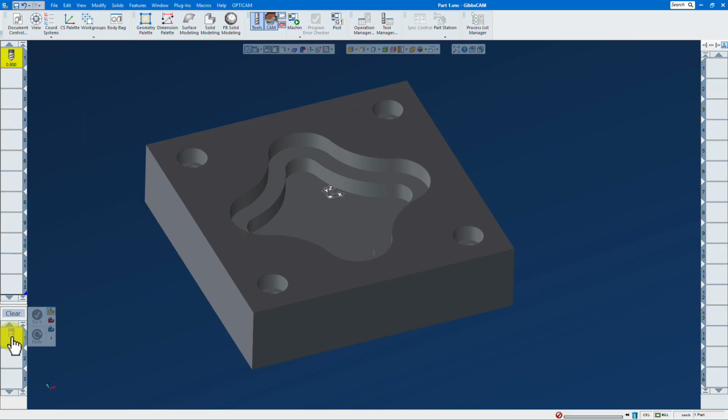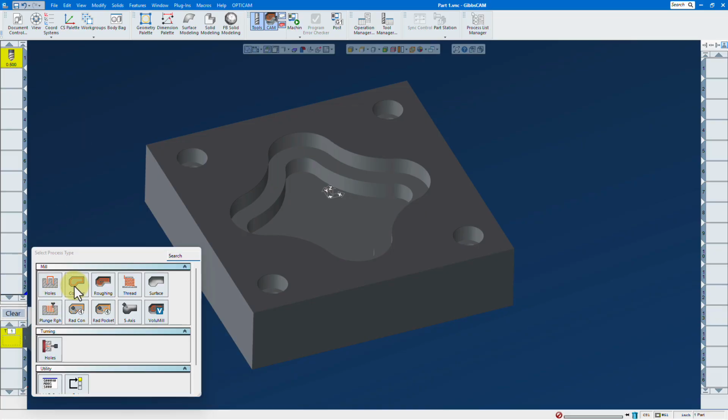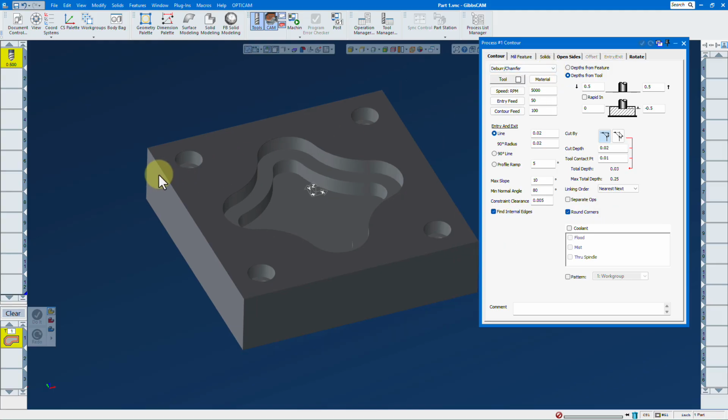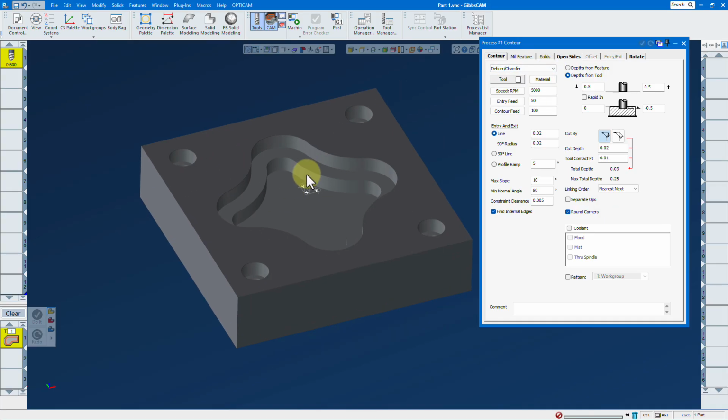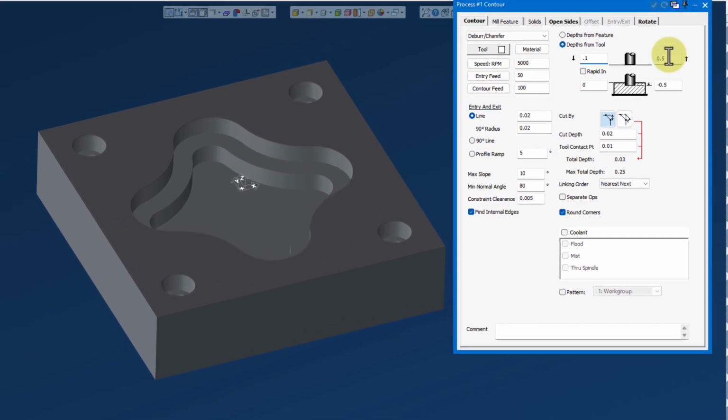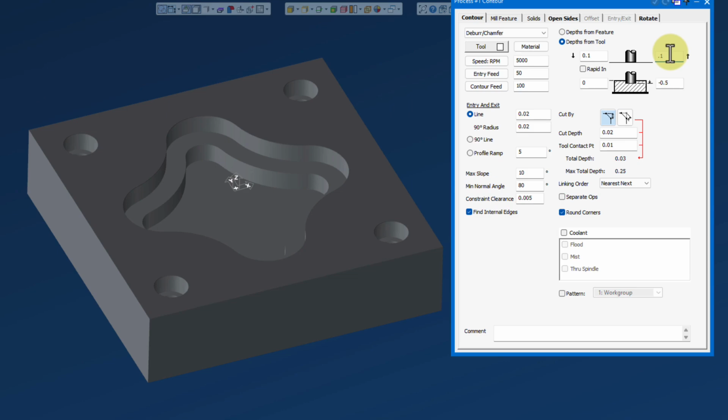Next, we'll bring this down and we'll select contour. And now in the pull down, we have deburring and chamfering. Okay. So here we set our clearances, whatever we want to set our clearances to be. Start, and then the depth that we want the software to see how deep we're going to go. So it looks at all the areas up to a 1/2" deep.